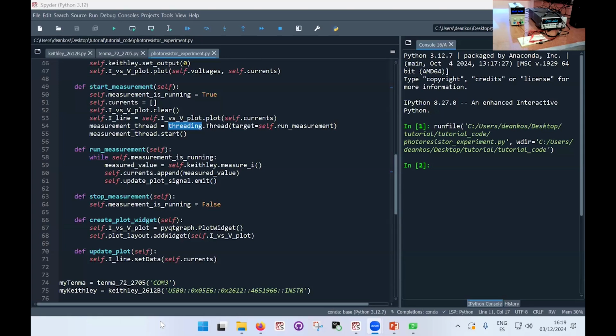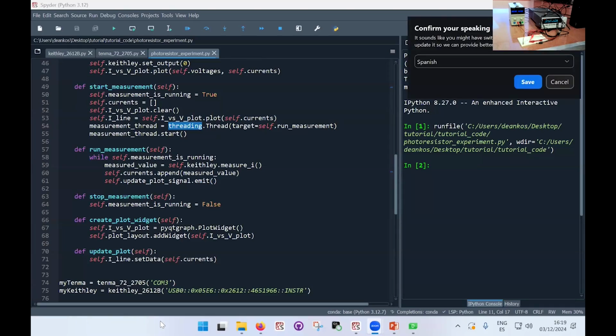You can program them maybe in Python for some settings to do certain things when they receive a trigger. And this trigger you will have to take from some hardware signal. So the Keithley on its back has a digital input-output port. I think it's about 25 pins. And out of those pins, you can pull a cable. You can have a look in the manual. The Keithley will tell you when it does certain things, or you can program inside the Keithley that when something happens, for example, a measurement terminates, a source value has finished outputting, or it terminates a sweep. There's a range of things that can trigger an event in the Keithley, and you can program it so that when this event happens, a certain pin goes high or goes low.